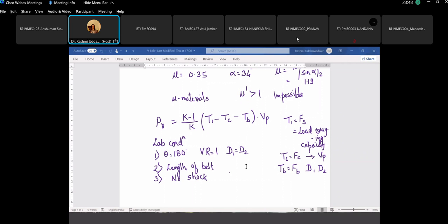What is given after this table? What is the next section in the V belt? Designation is given, which is saying that it is designated by its cross section and its inside length. This we have seen. Then we normally assume the ratio of diameters, which are inversely proportional to ratio of their RPMs. You can multiply with efficiency, assuming 98% efficiency.